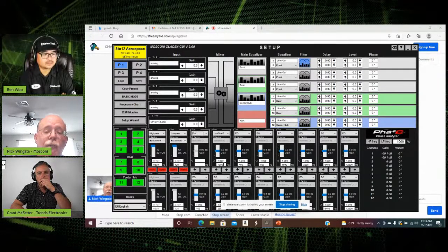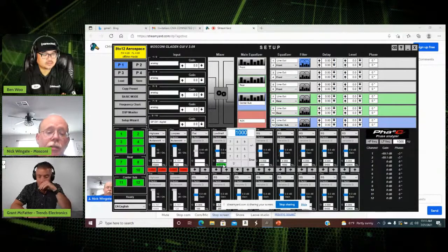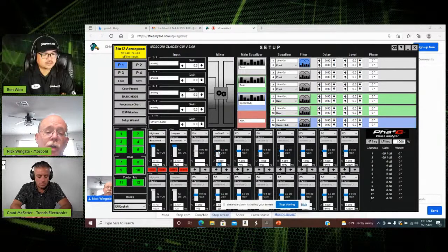If in the low shelf, I've got a mid-bass bloom, let's say from 400 hertz down to 150 hertz, and let's say it's 6 dB, I would just say, okay, from 400 hertz and down, I need to turn it down 6 dB. It's that simple. It really and truly is that simple. But it's a very, very powerful tool. And you can combine these. You may need a high shelf. You may need a low shelf. You may need it only on the right, or only on the left, or you may need it on both channels.